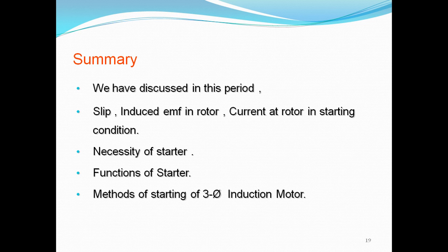If the current is more, then because of this current, it will damage the motor winding, and it will also affect the other motors which are working on the same supply.